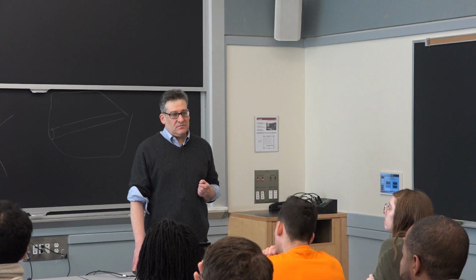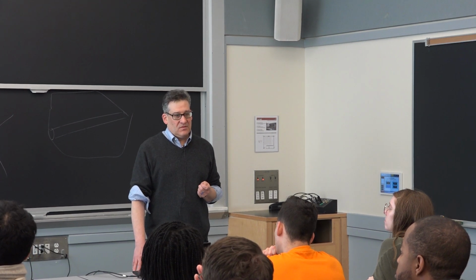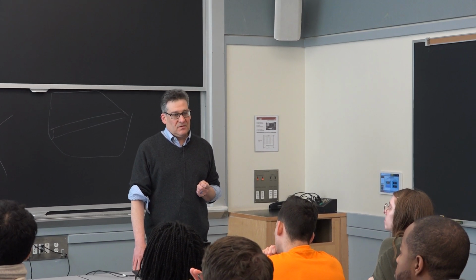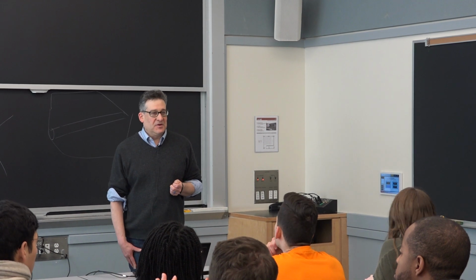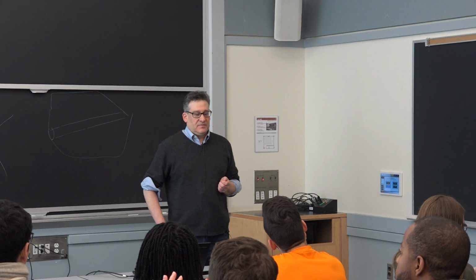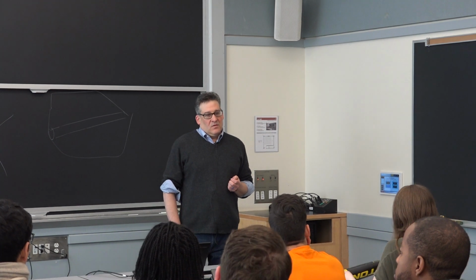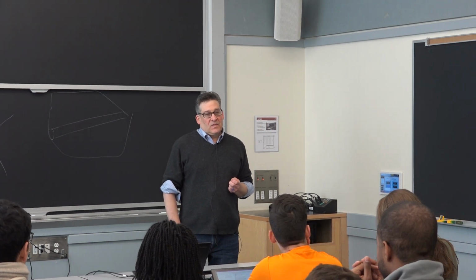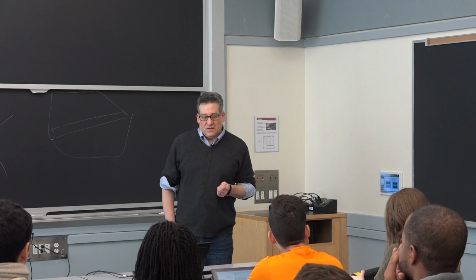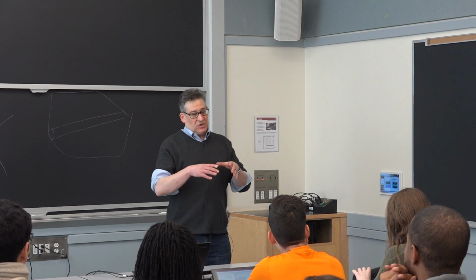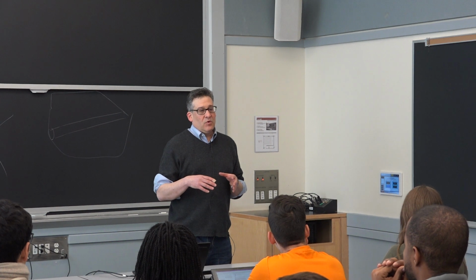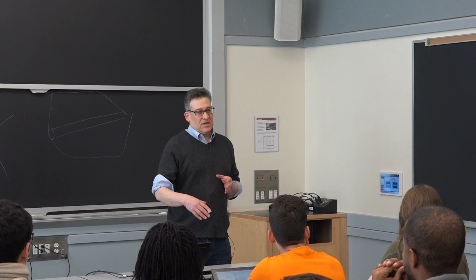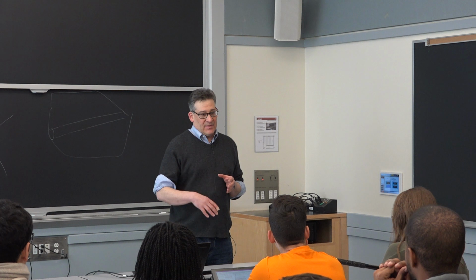So what you've talked about here is the loading of the vehicle. Is there also design for vibrational modes, mode shapes? Right, so what you're talking about is the natural frequency of the vehicle. Is that a bit less of a constraint than the loading? Well, it's the same thing. It plays into the design. That's when I showed you there was torsion load and bending load. What I didn't say is that they do more than static testing in that condition. They do both static and dynamic testing.